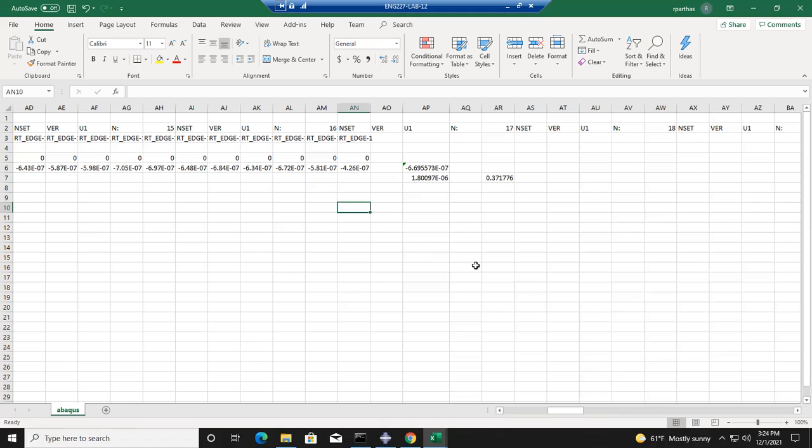You need to take a certain thickness and get the area over which the force is applied. Then you will get the stress. So basically we are converting the force to a stress and the displacement to a strain. Then that stress over strain will give us the effective elastic modulus. Is it clear? Yes. Great. We already got this one.